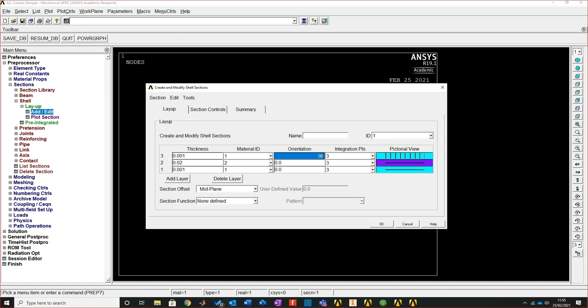You can often go 45, 90, 45, then 0, and it's about the reinforcement of that layout. But what I'm just trying to show here is how you can control that orientation. So if you wanted to build a lot more in depth in there, you could do that.